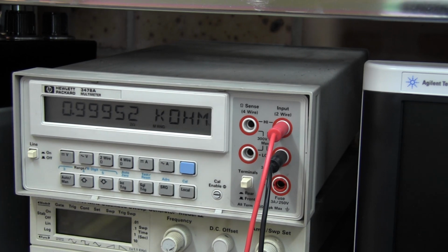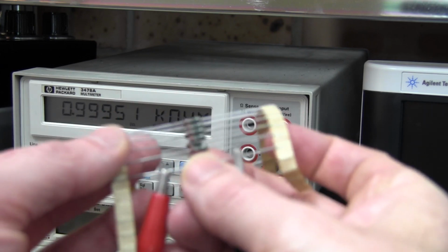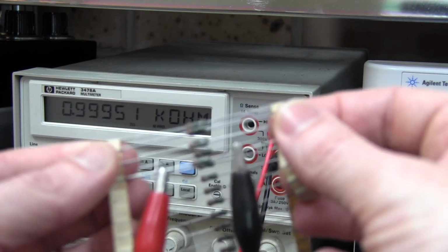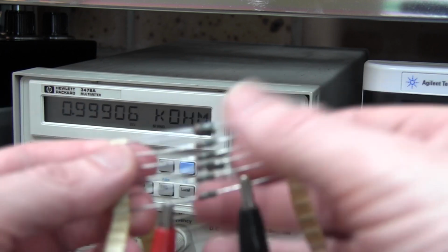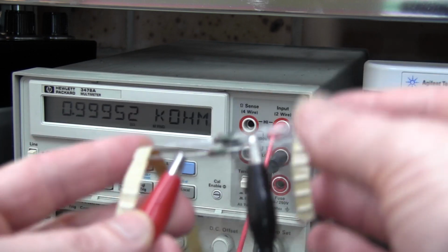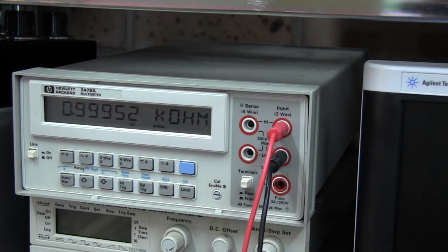But if you're doing this sort of stuff seriously, then you have to take those things into consideration. Any changes in temperature, just physically handling a single resistor like that can actually heat it up and change its temperature, even touching the leads. You're actually heating up that resistor. So handling can be important, those sort of things.